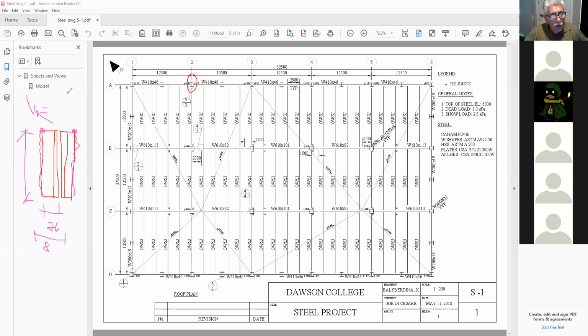You could use a 76 by 63 and make this even smaller, because what's important is the weld that you provide, the length of the weld here, and it's not the size of the angle. And that's what I'm trying to make you understand. And if you can't find anything that fits, you can actually ask the guy to cut this to the size you want, and then he'll provide the weld. It's always going to give you the same resistance.